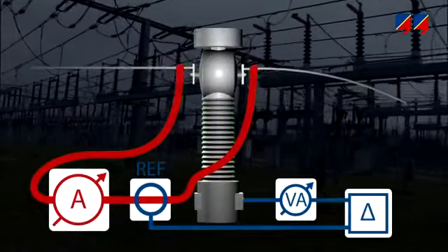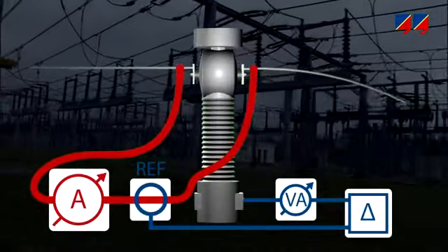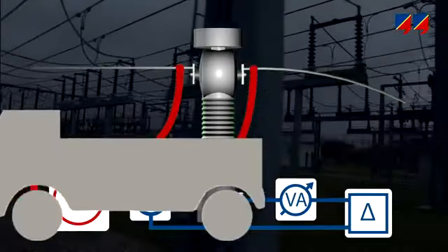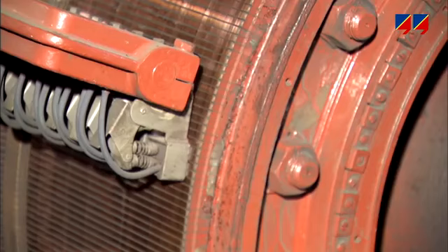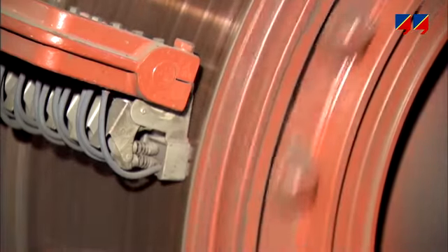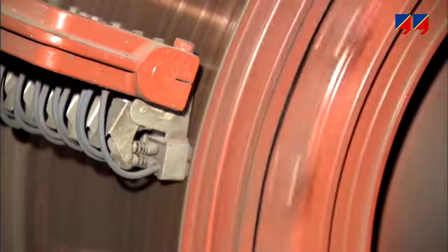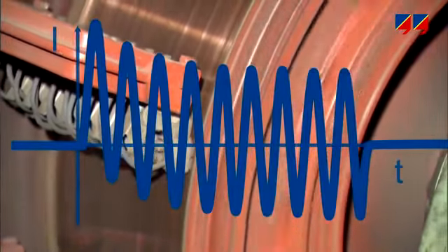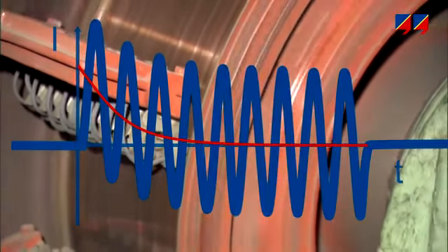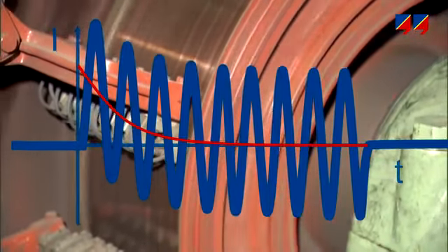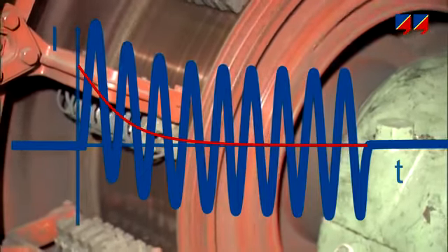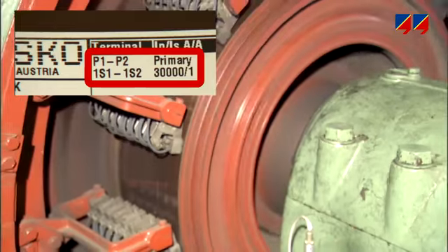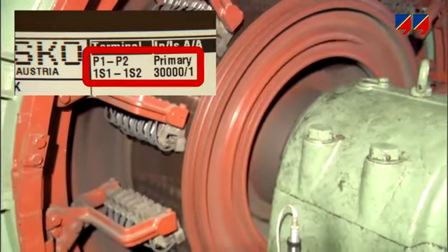This method is costly and laborious, particularly on-site, as heavy components need to be shipped and unwieldy cables are required for the current injection. Even this method reaches its limits where protection CTs designed for high short-circuit currents, high DC components in the fault current, or high primary time constants are involved. Such CTs require thousands of amps for testing them, exceeding the largest current source's maximum output current.